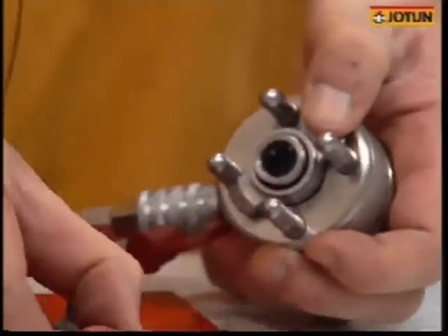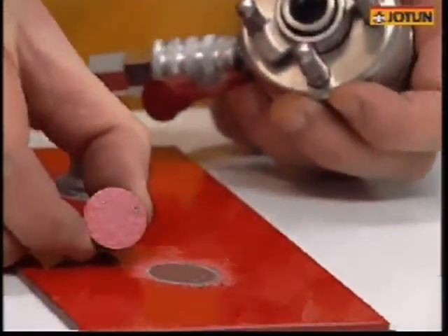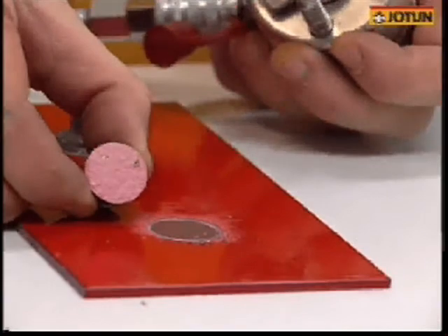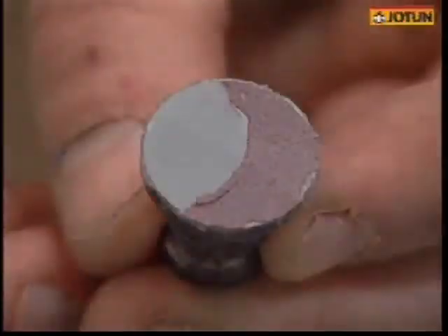It's important not only to look at the pull-off value, but also to look at the type of failure. This could be adhesion failure between coats to the substrate or a cohesion failure.